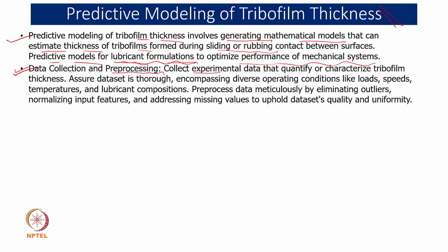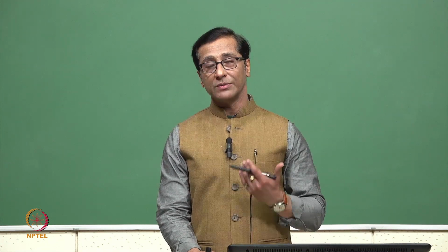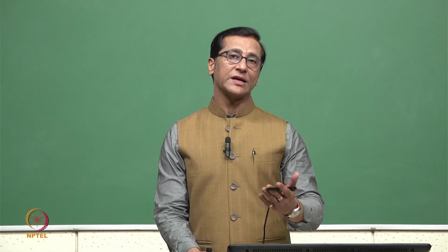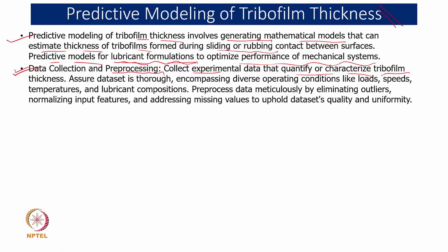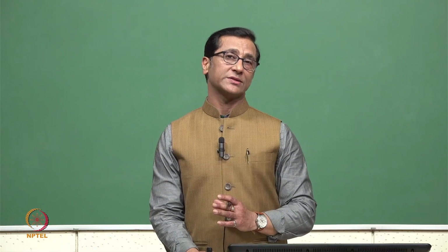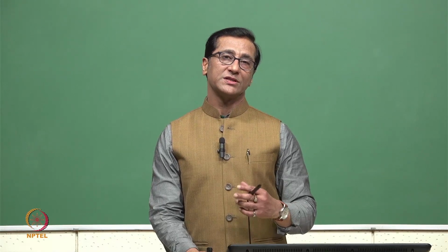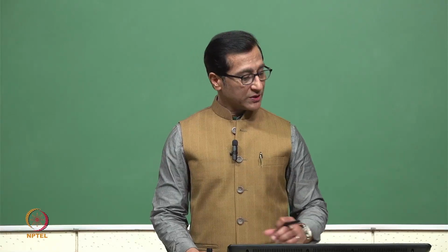What we do, we collect the experimental data which can really quantify the tribofilm formation, like whether it's friction force or debris or lubricant deterioration or thermal images, whichever. Because subsequent to this, after two or three slides, I'll be covering thermal imaging in one of the case studies. So whichever really symbolizes our tribofilm formation, we require those data, we require analysis of that. Like in one of the case studies I did using the proximity sensor, where two sensors are sufficient to provide what will be the film thickness formation. So that can be utilized.